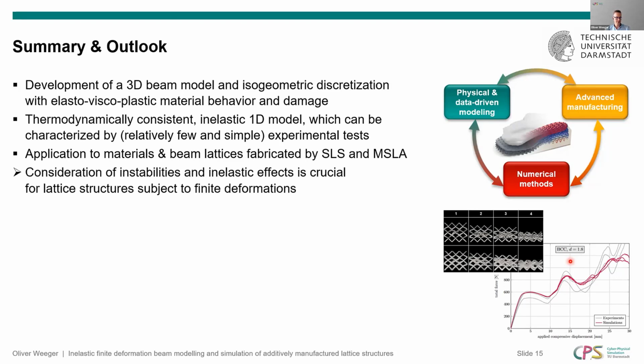As a conclusion, basically, we see that we got quite good agreements of the simulation and the predictions using these models. And it is really crucial that instabilities and all the kinds of inelastic effects are considered when lattice structures are subject to finite deformations.